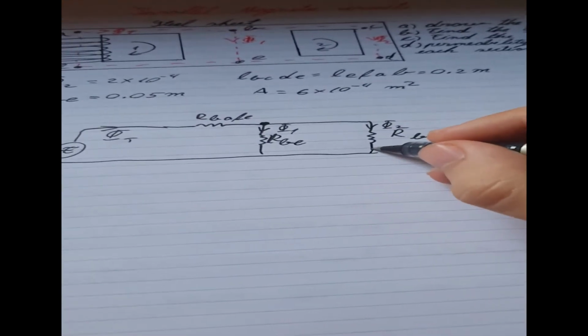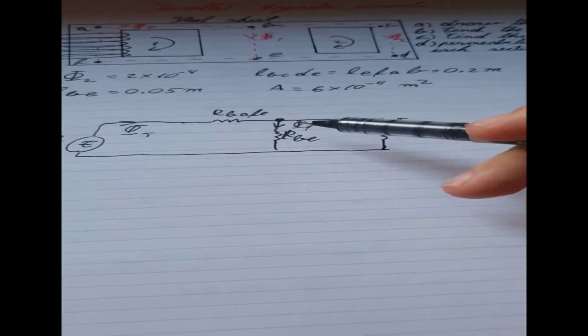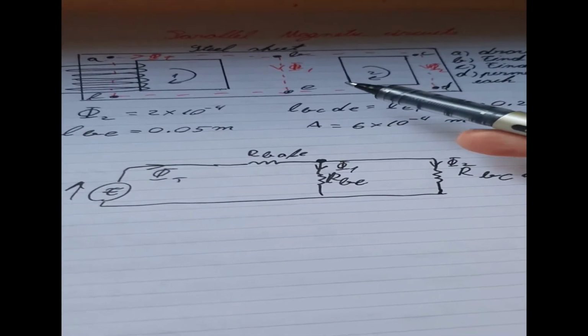Okay, so that's enough of drawing, to be honest. It's not necessarily always the material. If they are separate fluxes, you have to add in reluctances as well, because they are not the same. That's why doing this type of magnetic circuit is a lot easier in series compared to in parallel, and you'll see why. But anyway, let's get started.